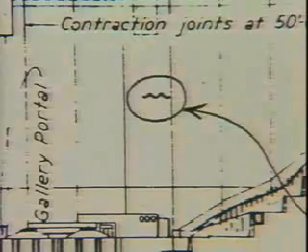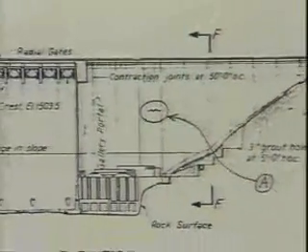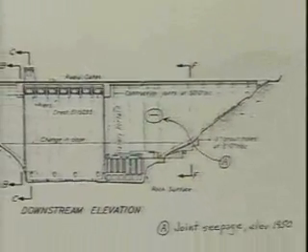In addition to the type of crack and its measurements, your description should include the direction of the crack, the depth if discernible, and any trends in direction or movement. Also, be sure to adequately describe the location of the crack, with reference to other features of the dam.